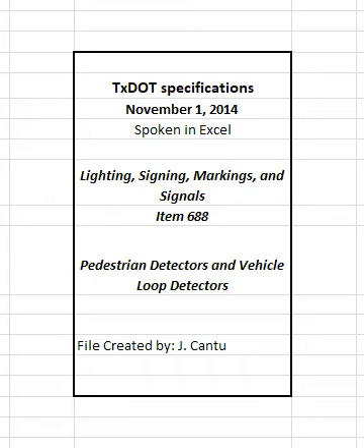3.2.1 Saw cuts. Cut the pavement with a concrete saw to form neat lines. Do not exceed 1 inch's depth on concrete bridge slab saw cuts. Cut all other saw cuts deep enough to provide a minimum of 1 inch's depth of sealant over the wire. Make a separate saw cut from each loop to the edge of the pavement unless otherwise shown on the plans. Ensure the cut is clean and dry when the wire and sealant are placed.